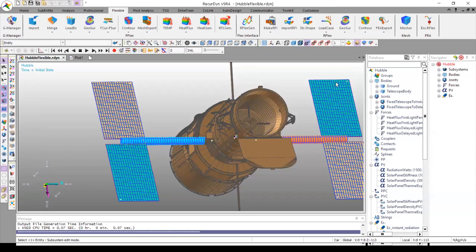And with very large and flexible solar panels, you end up with that kind of bimetallic effect, even though it's only one material. One side is hotter than the other for some period of time, and if the stiffnesses of the system are wrong, then you can end up with this beginning to flex and then inducing vibrations in the system. Very large spacecraft are very flexible. You can't afford to send a bunch of steel up, so we end up with these very large flexible structures in space.